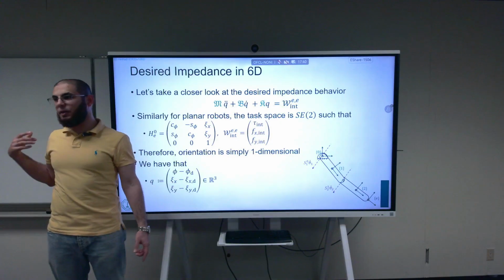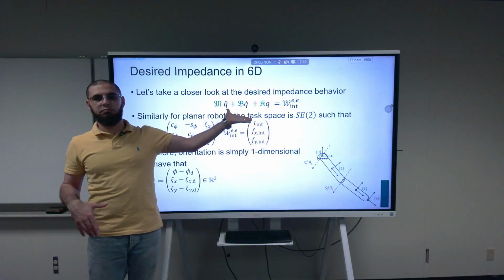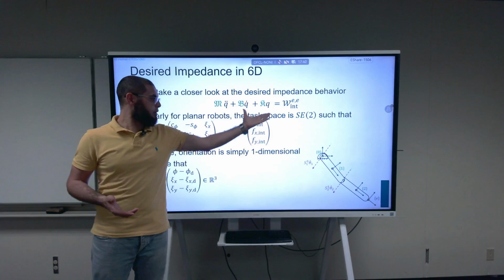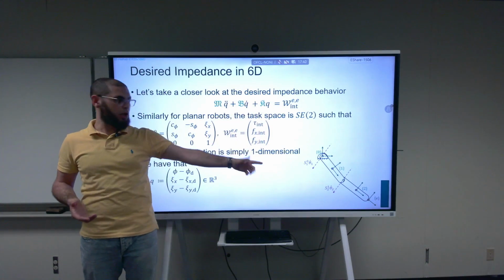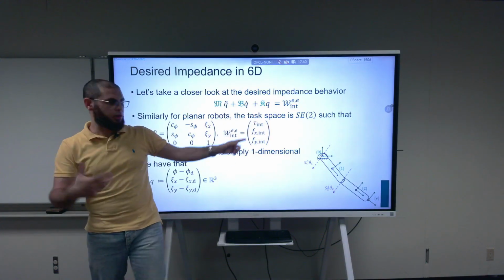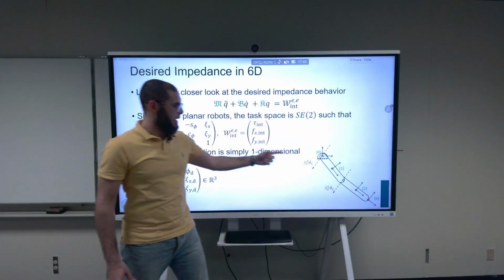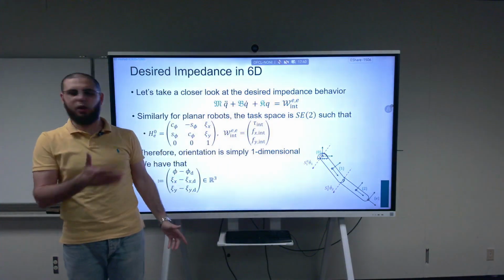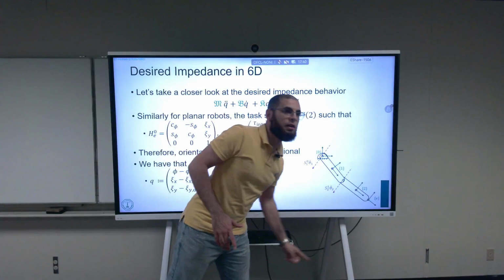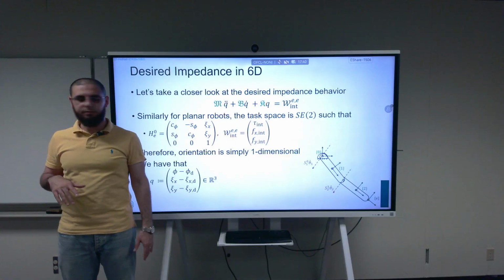So the example I showed you last time of the two-link robot arm in the simulation was also very easy. It was also Euclidean impedance. Okay, we had simply R3. And the interaction wrench, because this is a planar case, we have only interaction torque at the end effector, something that's rotating like this, and you have force in the x and force in the y. Of course, depending on which frame, here we're talking about the end effector frame. So this is the x and this is the y direction. And of course, you can transform everything with this joint if you want.